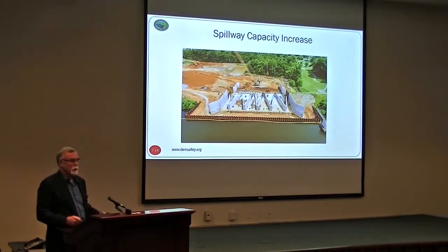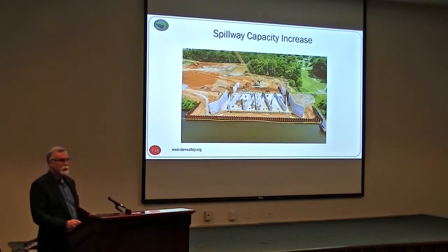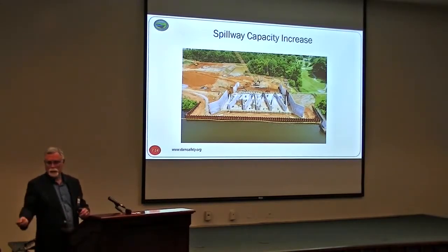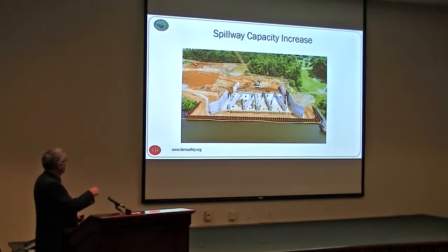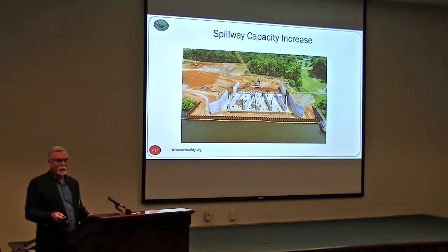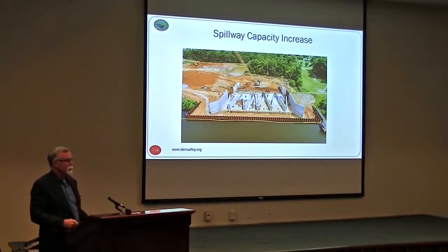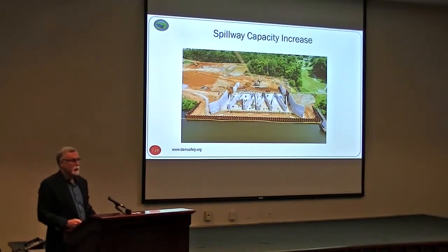This is a bigger one that's ongoing in Virginia. Another NRCS flood control water supply dam. They closed off the emergency spill, which was, to use the right word, the auxiliary spillway. That was over here. It was an earth spillway that was studied, and it was found that it would fail if you had the design storm. So that spillway has been closed off, and now this is the new auxiliary spillway. Here's the riser for the principal spillway right here, the pipe coming out right there. So here is one of the 5-cycle labyrinth spillway. That is an $8.5 million project.